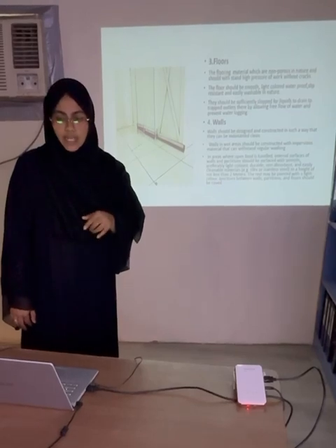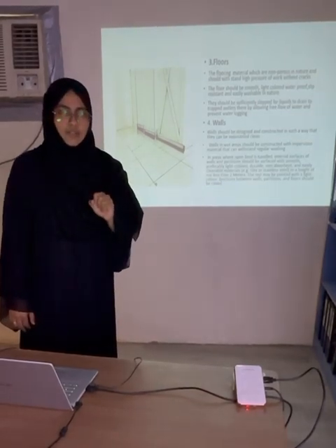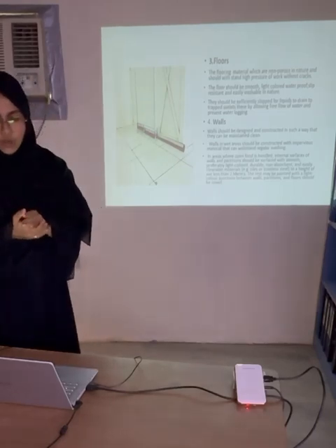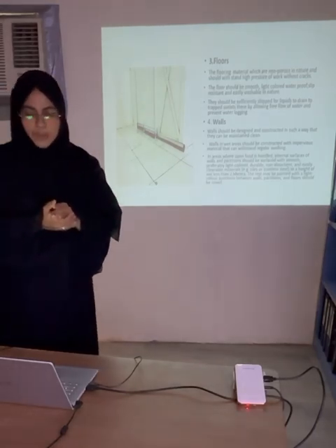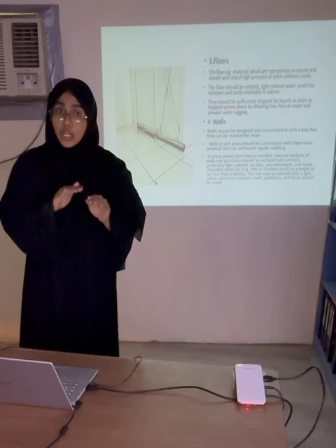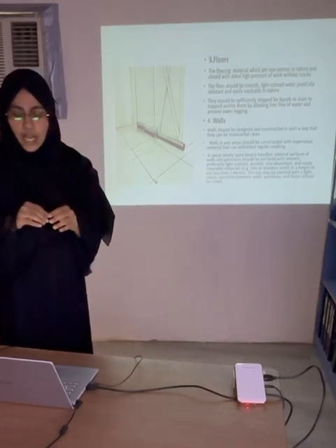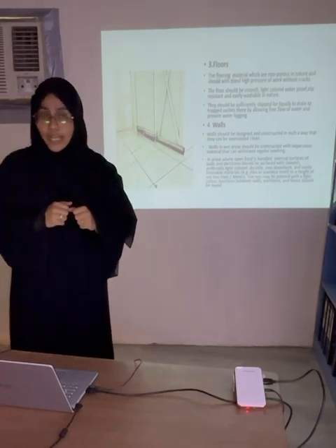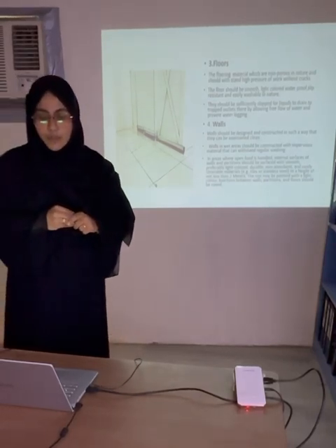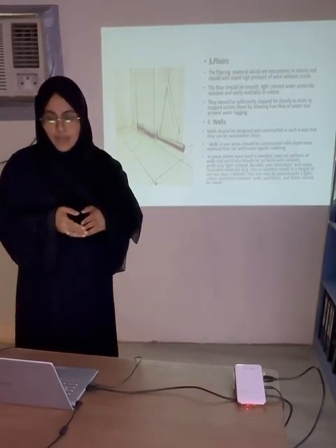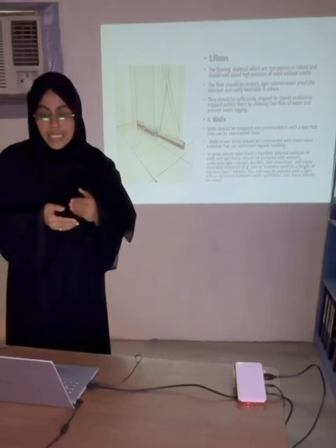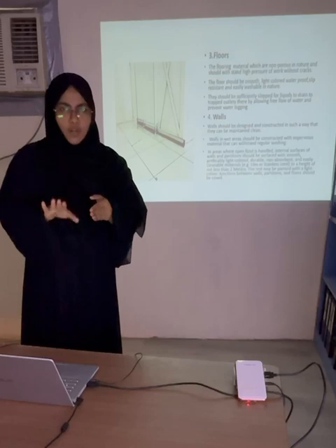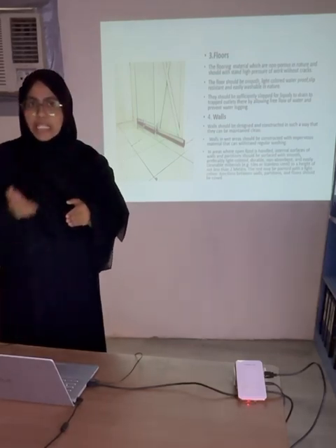Next, we will be discussing the floor and how its design should be. Inside the production area, the floors should always be made of non-porous material of high quality, which can withstand high pressure without any cracks. The floor should be smooth, light colored, waterproof and slip resistant, because chances of standing water will be there. So it should be easily cleanable also.